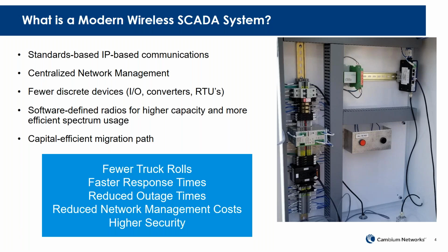We also do some integration things like Modbus TCP to RTU conversion, which can also eliminate external boxes. And we'll talk about a wireline replacement feature, which can eliminate RTUs altogether for certain simple automation applications. These are all software-defined radios, so down the road we can push firmware updates to these.